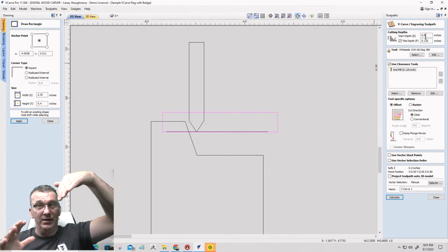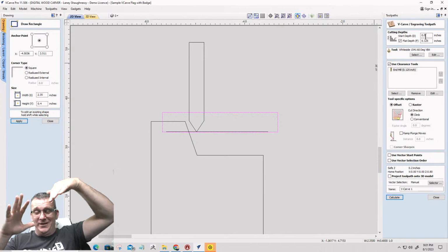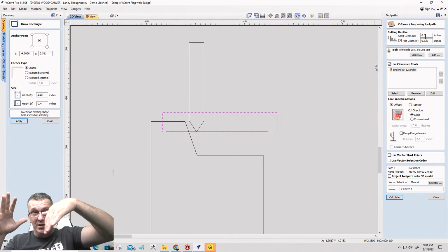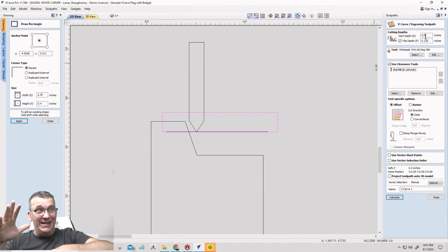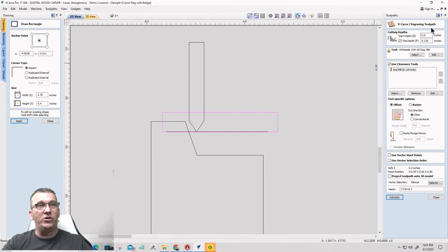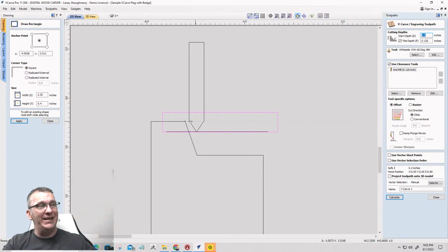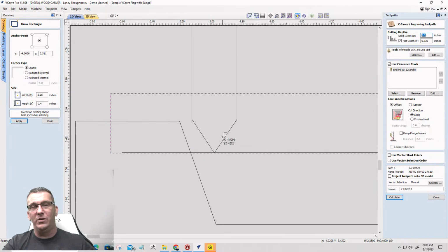It's plunging, don't stop, don't pass go, don't collect $200. It's plunging past that start depth. That's where it's starting, and it's going down to its next cut depth, right? That's just the start point. So if your start point is too big, then your bit is plunging into a massive amount of wood that's still there.